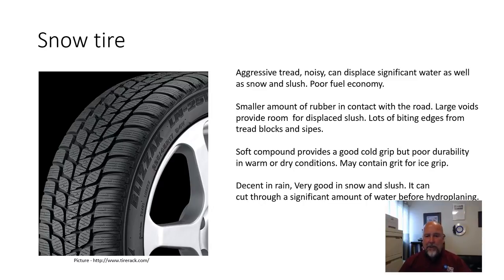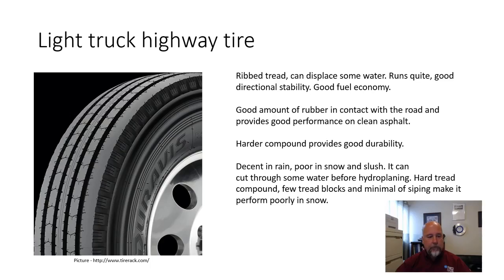That doesn't necessarily mean they work well in the summer, though. Typically, all those things that go to making it grip the ground in the winter make it wear quickly and make noise and whatnot in the summer. So snow tires, although they do provide a definite improvement to vehicle performance in the winter, they typically are not so good in the summer.